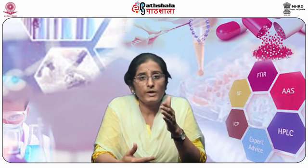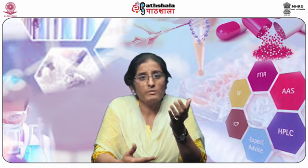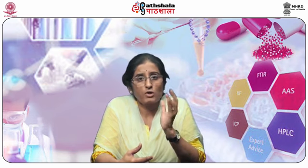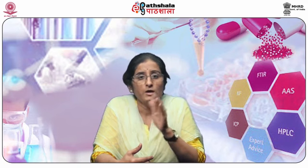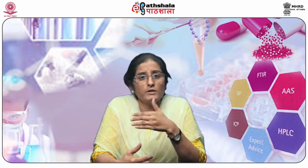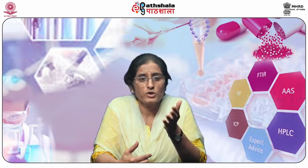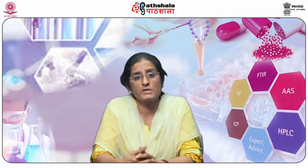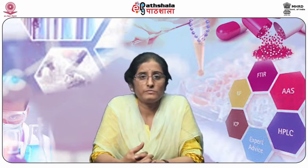The mechanical property of plastic can be altered by some solvent systems. Examples: oils show a softening effect on polyethylenes. Polyethylenes and polyvinyl chloride are attacked by fluorinated hydrocarbons. So one should be quite careful about what type of material he is storing in the plastic packaging material.